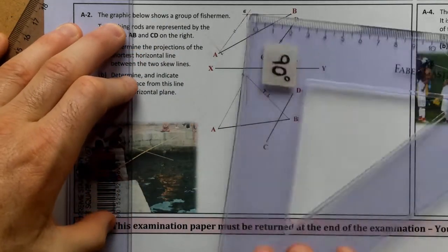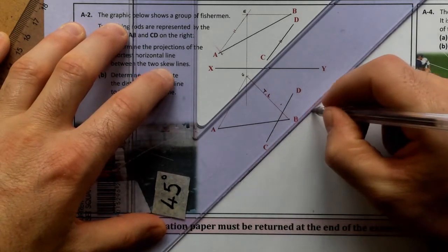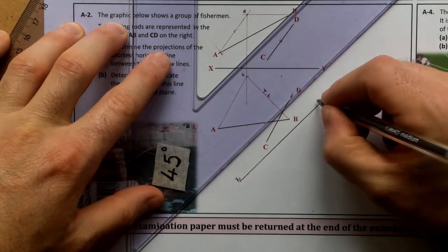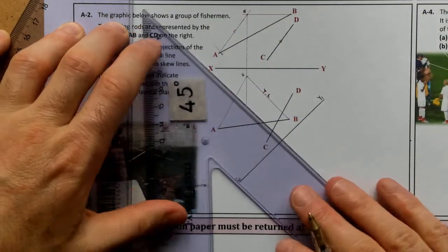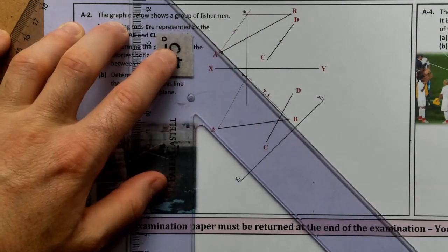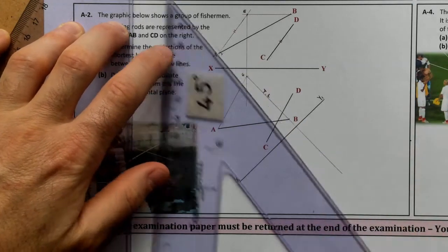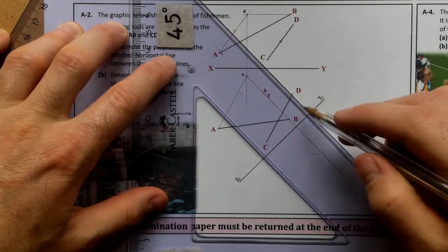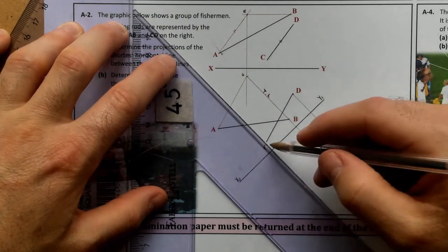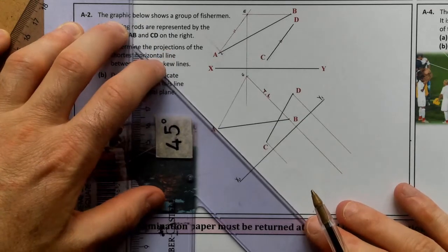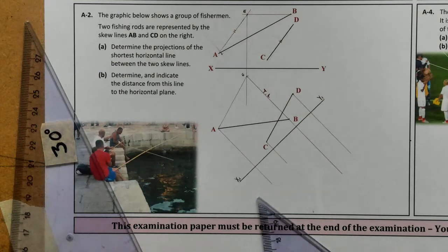So I'm going to swivel that about, and I'm going to set up an x1, y1 just like that there. So just make sure I'm still happy with that. Yep. And now I'm going to project out perpendicular to it from all those points. So B will have to come out a little bit further, something like that. Likewise with D, so now to there. Do the same with C and A, don't seem to come out as far. Somewhere like that. And if you project from the plan, you take your heights from the elevation.